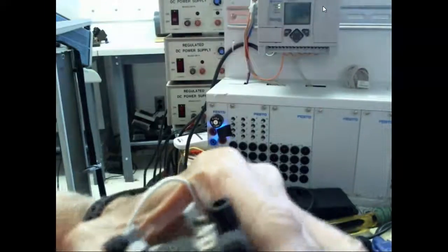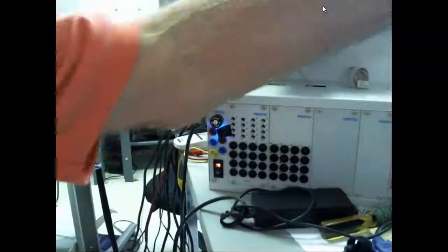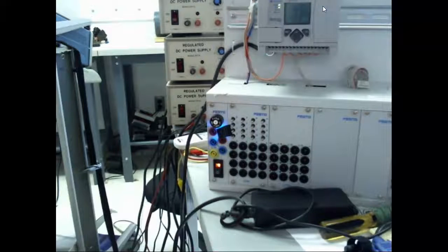Single pole, single throw. Most of them would just give you the number of poles that have it. So what advantage does double break have over single break? These are double break contacts. I can show y'all some push buttons too that are double.